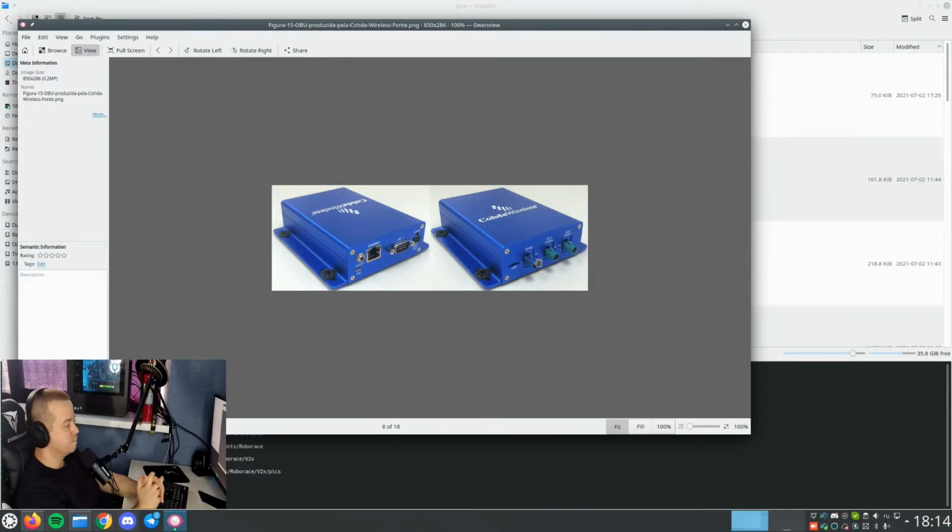It has a GPS sensor installed inside, but on the missions we are using external hardware that provides us with high precision GNSS data, the OXTS sensor, and OXTS sends data to the OBU over the onboard network.